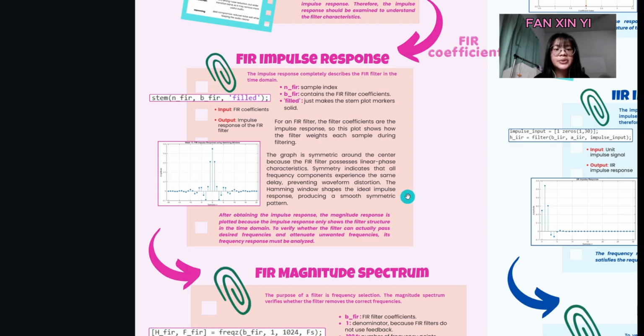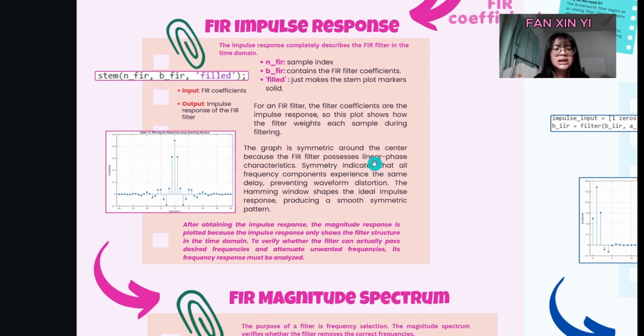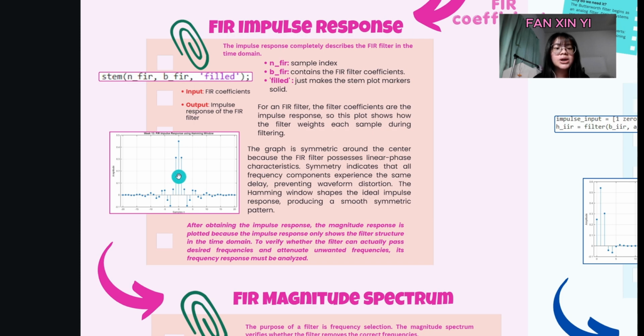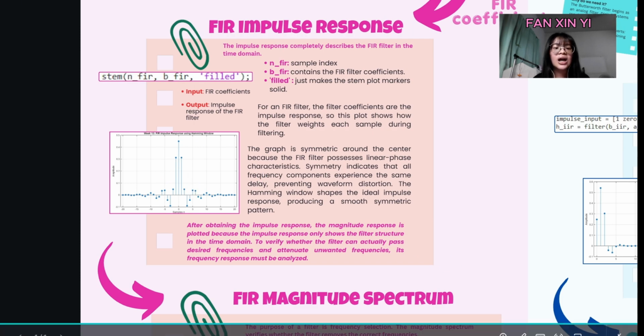Next is the FIR impulse response. The impulse response represents the FIR coefficients. As we can see, the FIR response from MATLAB is symmetric about the center, indicating a linear phase FIR filter. This means all frequency components experience the same delay, preserving the original waveform shape.